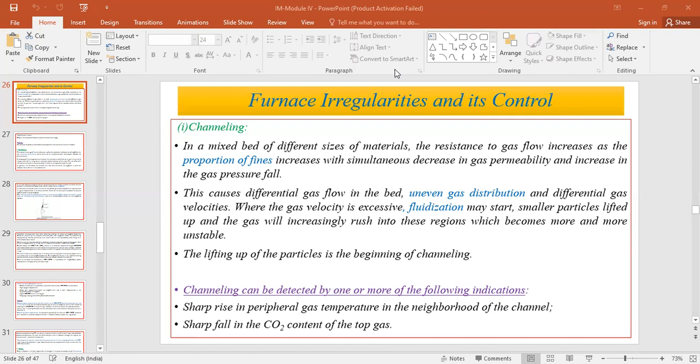This is because whenever these reducing gases, especially CO gas, are highly stable at high temperatures in front of the tuyeres, and when this CO gas travels upwards and reaches low temperature, it loses its stability and readily reacts with iron-bearing material and tries to transform into CO2. This CO to CO2 transformation takes place when there is a very good interaction between the solid and the gas, that is, gas-solid interaction.